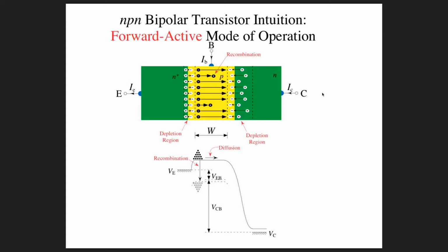Okay, in this segment we're going to pick up and continue talking about the bipolar transistor operation. And I want to go back and bring out something which I forgot to bring out when we were talking about the forward active mode of operation. I did mention that the current flow in the base here was by diffusion, and if you recall, diffusion is a mechanism of carrier flow that doesn't depend on having a potential difference, which means an electric field in a region.